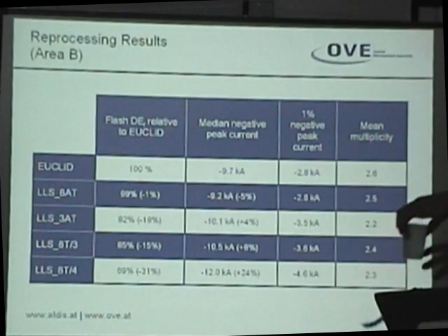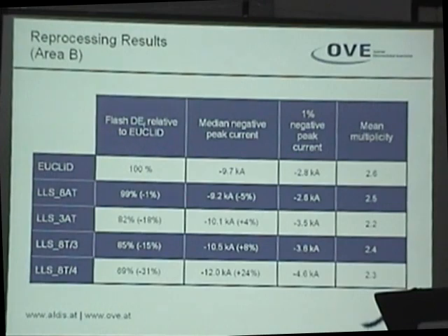Well, of course, we don't know. I've seen positives of at least 2.7. Real positives, 2.7. But positives are not calibrated, and so the negatives, the first strokes, are also not calibrated. We have seen negatives down to 2 point something also. Then negative subsequent strokes that are real, but never seen one. The problem is that we rarely see a first stroke at the Gaisberg, and also with such small peak current.